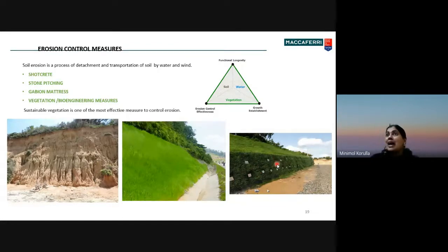Then the last one, which is again the same Tamil Nadu Kerala border I talked about. There is a slope, and this slope is stabilized with nails and the front fascia. I added this photo because we can see the nail points and the plate, as well as the slope being almost vertical, and we can see an engineering mat, not a bioengineering mat. It is not coir or jute, but a polymeric product, and through that we can make a very aesthetically pleasing slope with good looking trees planted.